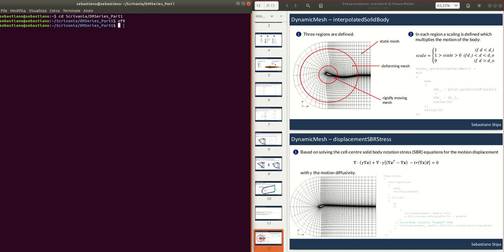So basically you use the Extrude Mesh, you take the surface mesh onto a patch, which is, let's say, a strictly 2D mesh, which is this one, but you have to think about this as a 2D mesh, a face mesh, not a cell mesh.